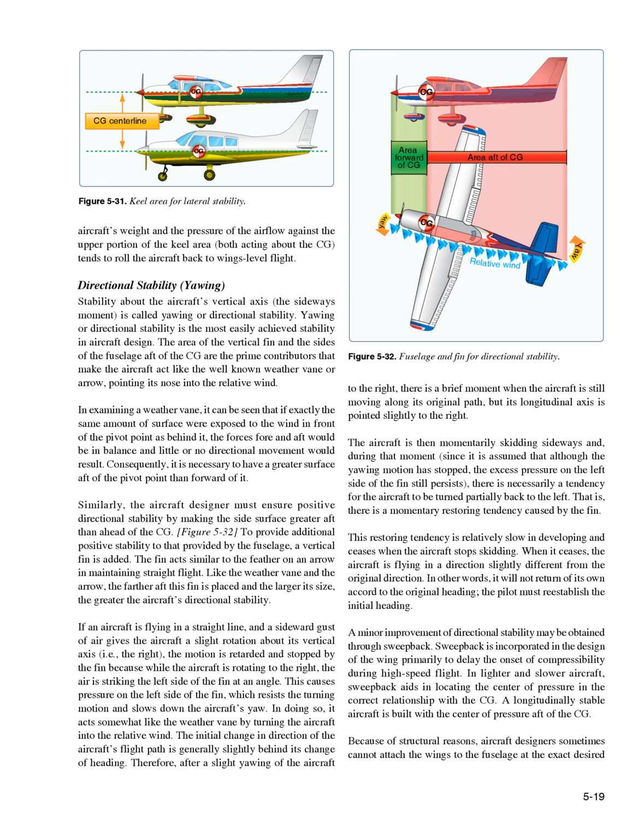This restoring tendency is relatively slow in developing and ceases when the aircraft stops skidding. When it ceases, the aircraft is flying in a direction slightly different from the original direction. In other words, it will not return of its own accord to the original heading; the pilot must re-establish the initial heading. A minor improvement of directional stability may be obtained through sweepback.